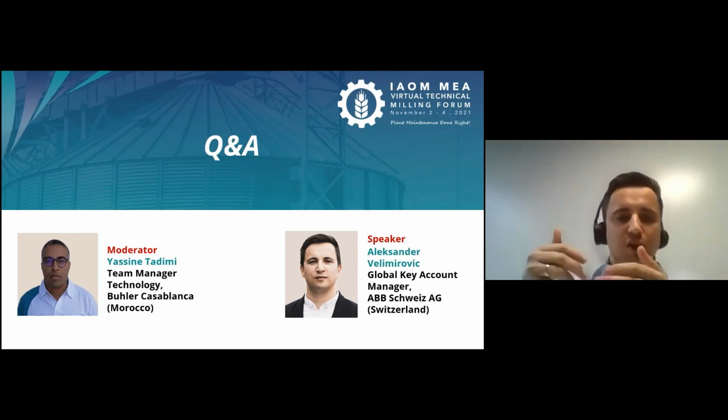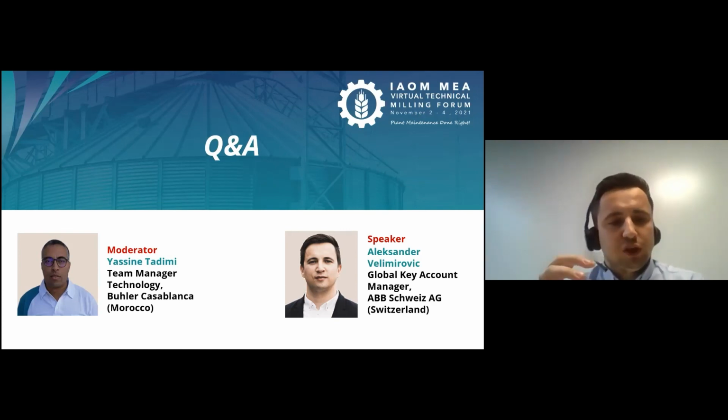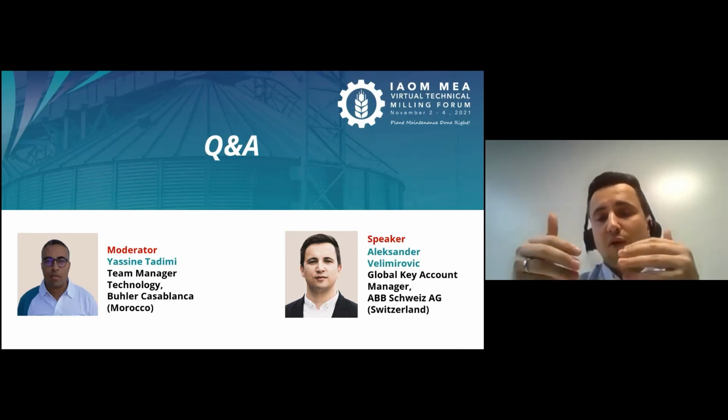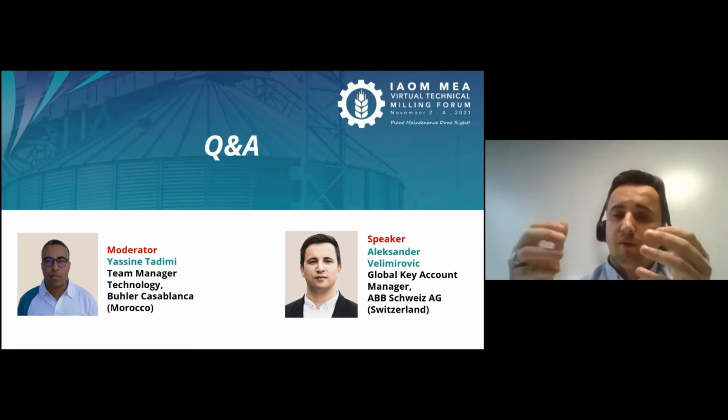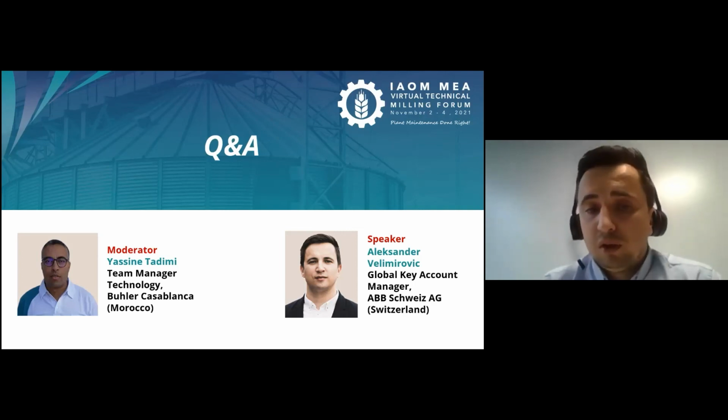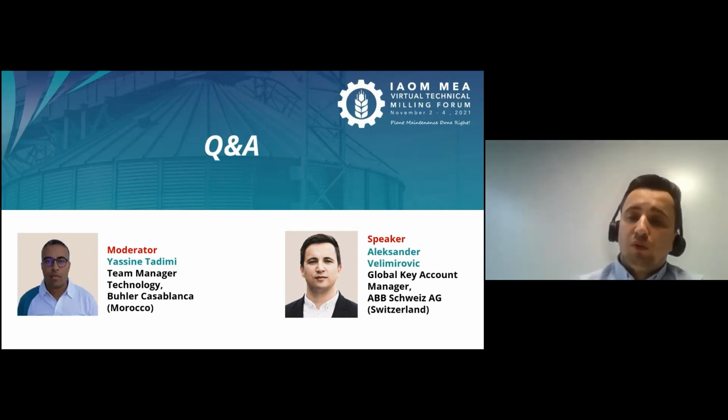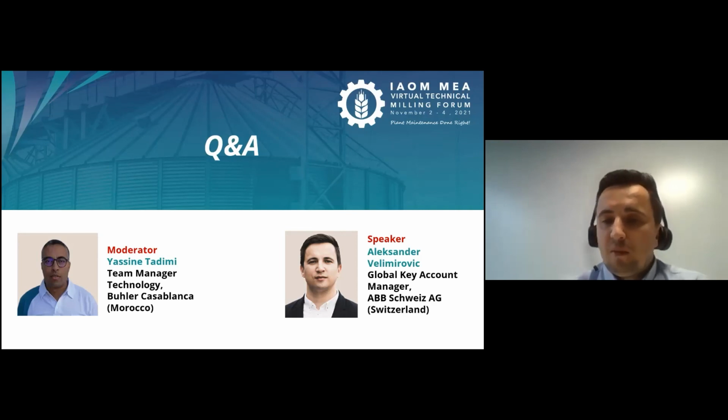And regarding high efficiency, as an example, if you have an i3 or i4 motor, they are very high efficient, cool motors which operate at a very cool level. So they're not heating up very much. If you want to go straight away and easy, you can use an 8% derating factor for this 8 degrees Celsius additional temperature, or you can speak to your motor specialist like ABB. Then they can see what the temperature reserves are for those motors.